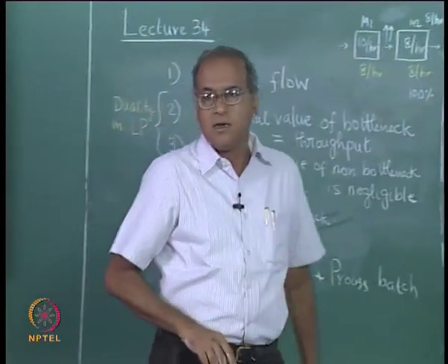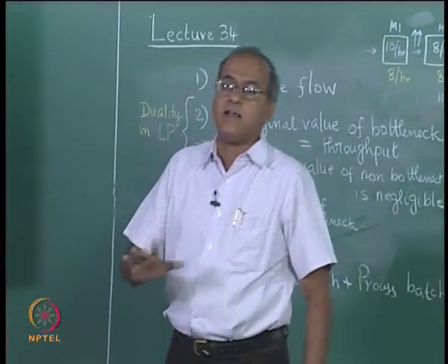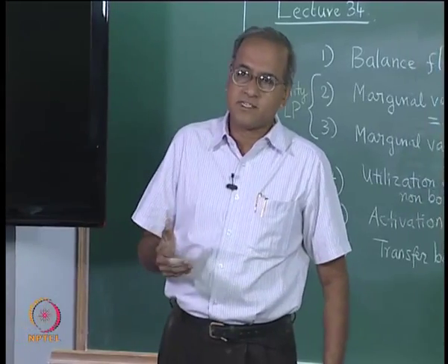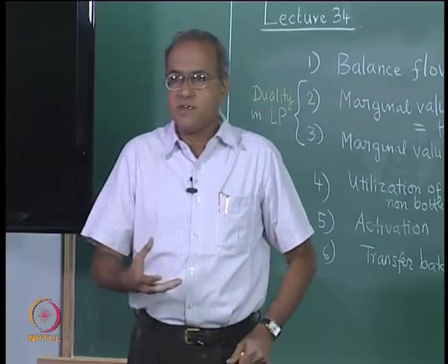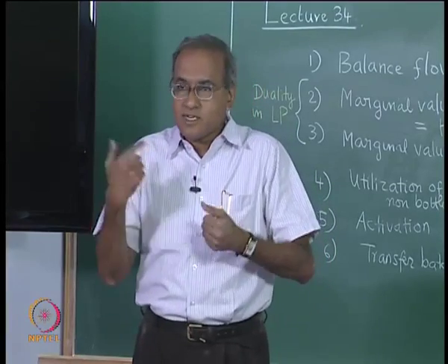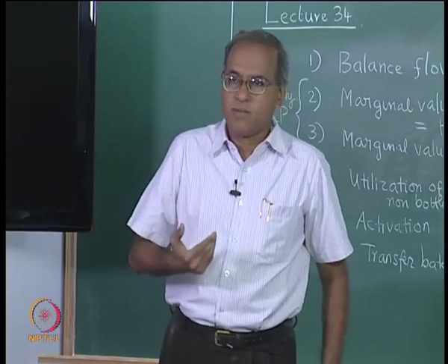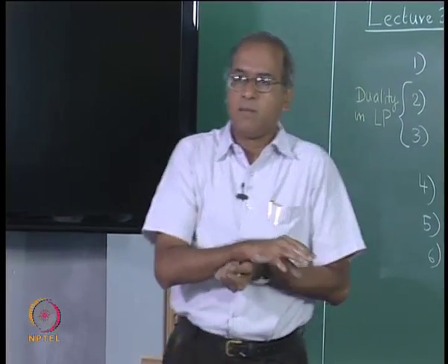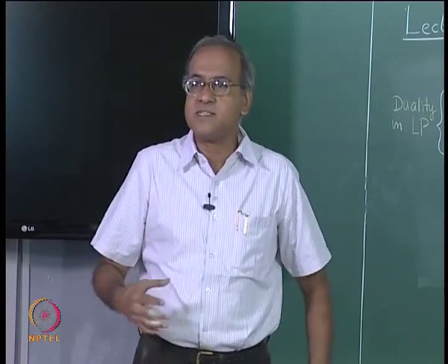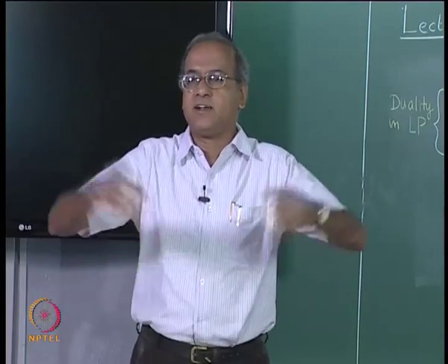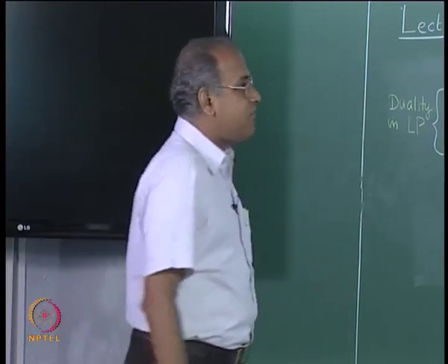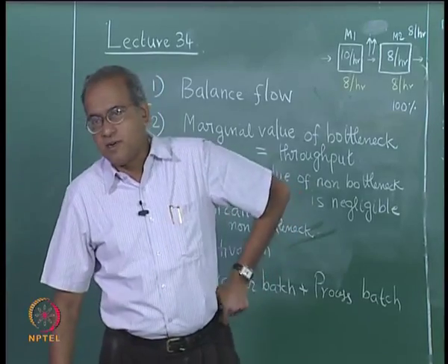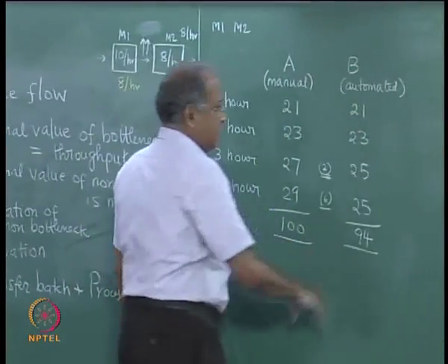Synchronous manufacturing does not necessarily ask for relocation of machines. Synchronous manufacturing principles are used when the layouts are not changed to bring them to cellular mode. It may be possible to use these ideas in the cell as well, but this can be used in situations where machines are actually located far away. So, if transportation batch or transfer batch is equal to the production batch, then in this case we will need one extra hour.